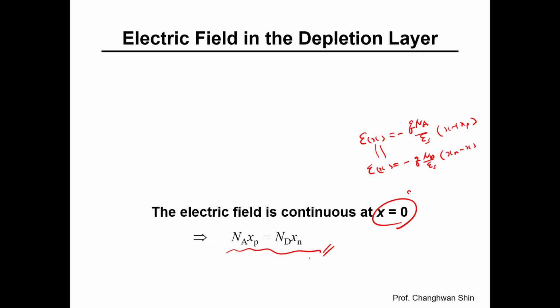Okay. So this principle is extremely useful in device design. By controlling the relative doping concentration on each side, we can engineer how the depletion region distributes itself, which affects properties like capacitance, breakdown voltage, and switching speed. In particular, for the one-sided junctions we discussed earlier, P plus N or N plus P, the depletion region exists almost entirely in the lightly doped side. This simplifies our analysis even further and is a common design approach for many practical devices.